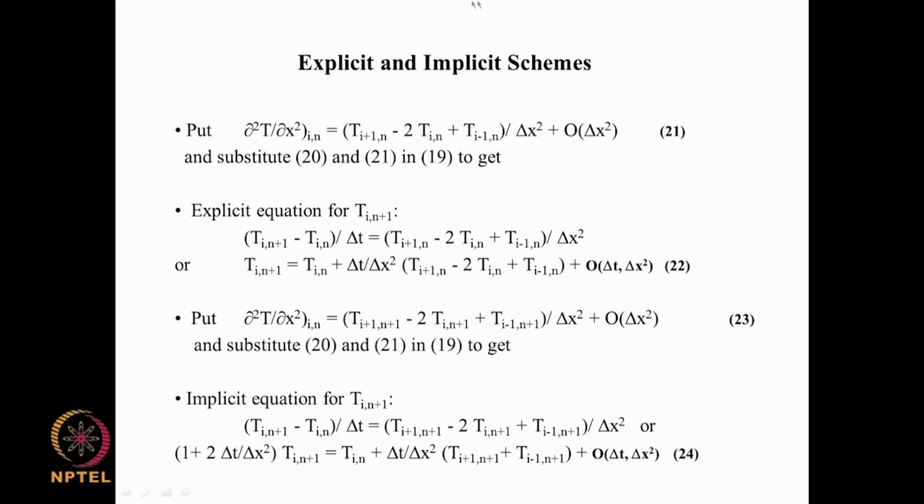For example, if we want to evaluate equation 22, this is a time dependent problem, and it requires an initial solution. So, that means n equal to 0, or n equal to 1, is the initial guess or initial condition, and the initial condition is given over this entire space domain. So, as part of the specification of this problem, we are given the values of T_i^1 at every point.